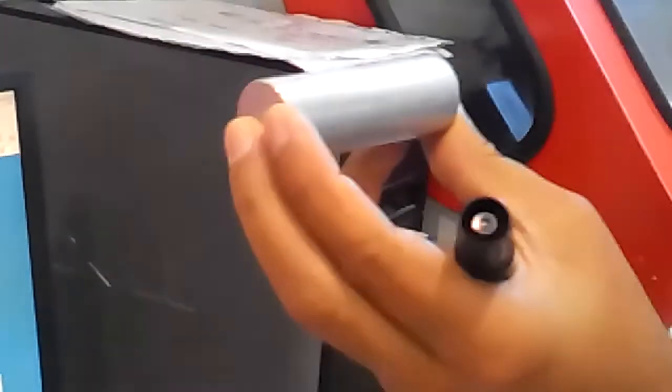Go to the manual mode, make sure the feed is low, click on Z plus. Here you have to make sure which axis you are pressing, because once the tool has touched the workpiece, if you click X and press minus, it will keep digging. It damages the machine and the workpiece. So make sure when it touches material, always move the Z and go minus now, so that you can clean the workpiece.